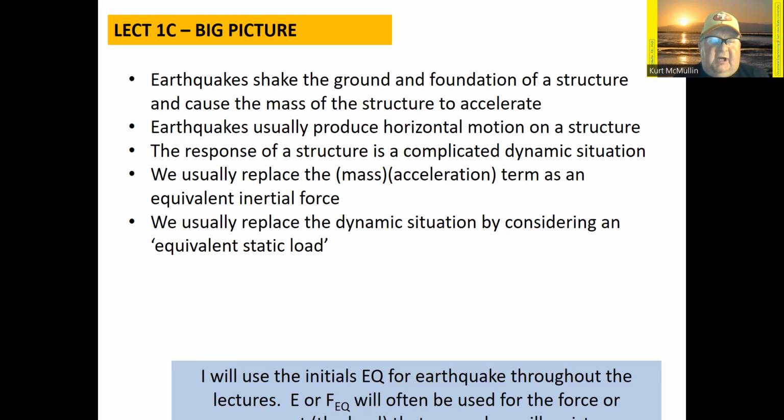So the first thing we generally do is think of the mass being accelerated as really being an equivalent inertial force. And instead of considering the dynamics of the earthquake motion, we're going to replace that with what I'll call an equivalent static load that we can use in combination with the other loads we need to design buildings for. I generally use the initials EQ, meaning earthquake. I'll try to be consistent through most of the slides that way.